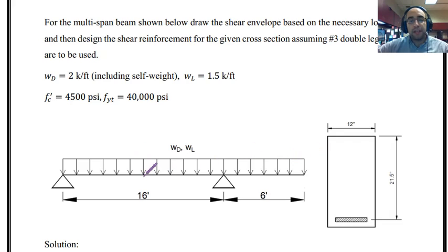For example, when you had this course, we said, if I want to know the maximum moment at the middle of the beam over here, I have to draw the influence line, which meant considering a hinge over here, pull it up, and then this will be the influence line for bending moment at this point.